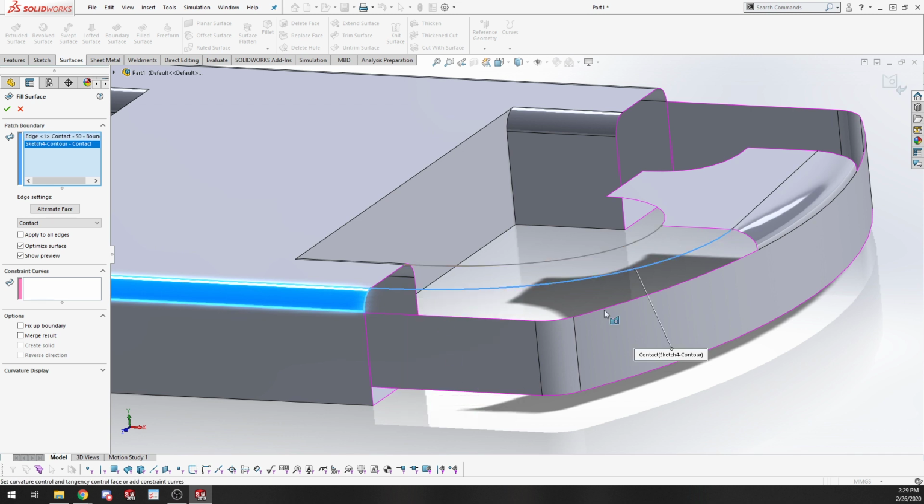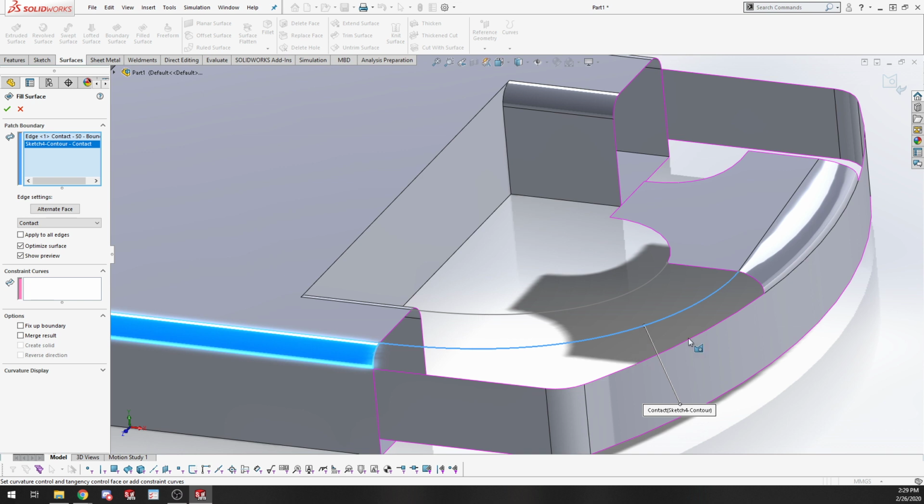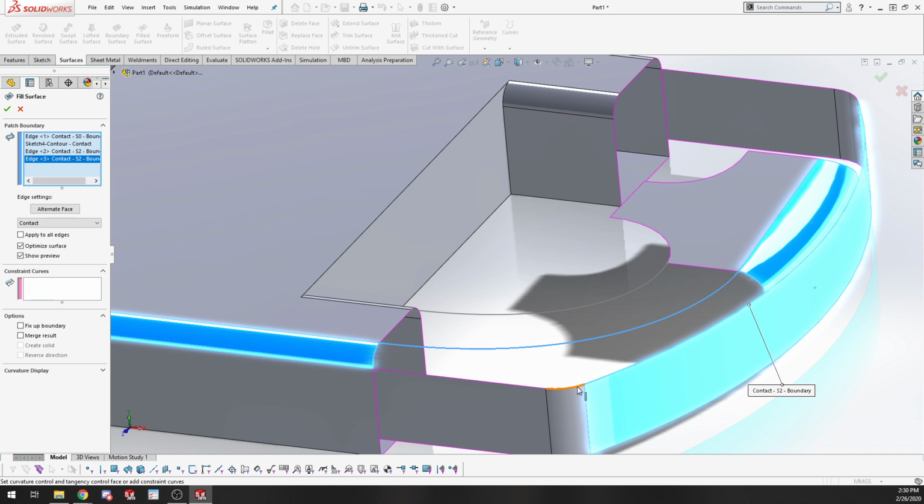Contour selection, maybe. That's weird. Either they changed this up or I'm thinking of something else. But basically, I can just select individual sketch entities instead of selecting the whole thing. In the past, what I'm thinking of is a selection manager thing that you can use to select. You can choose to either select several edges together and treat them all as one line, or you can select a face, and it lets you filter through what you're actually trying to select. And then I can select contours, I guess. But that allows me to, instead of selecting the whole sketch, just select that one line. And then I can go through, again, do the same stuff that I was doing before.